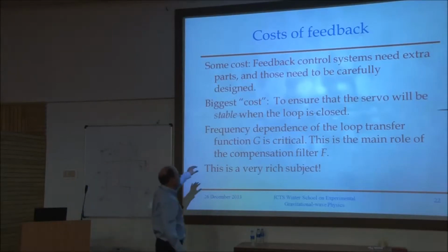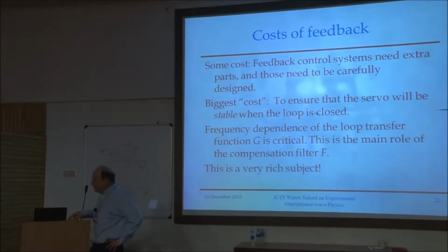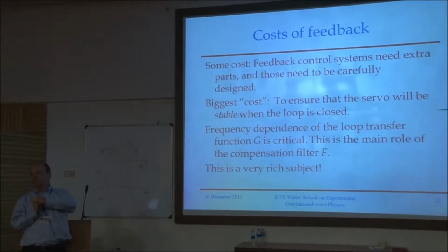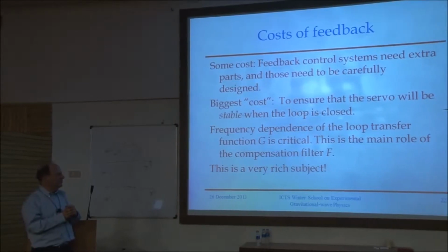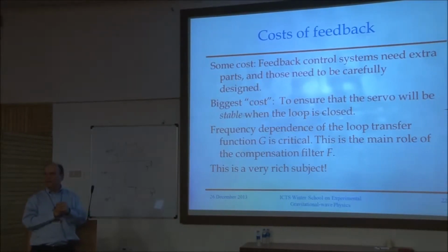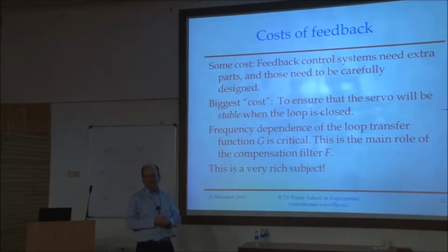And now we come to what I want to say about the filter F. That's the place where you try as hard as you can to achieve your performance goal. Try to make G big every place where you would like to modify the original frequency response of the system, the open loop response. But it's also the place where, if you're not careful, you can actually introduce problems that will cause the system to go unstable. And therefore, it is the battlefield where you have to step back from your overambition and modify things so that the properties are okay.